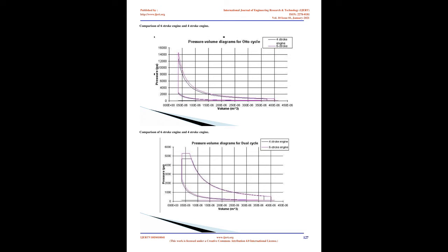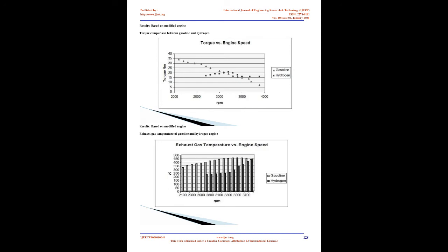Hence fuel is injected once in every 3 cycles of the crankshaft, whereas in a 4-stroke IC engine fuel is injected once in every 2 cycles. Cycle of 6-stroke engine, graphical representation. Following is the graphical representation of the 6 strokes in a cycle. The crankshaft rotates a total of 1080 degrees in one complete cycle.